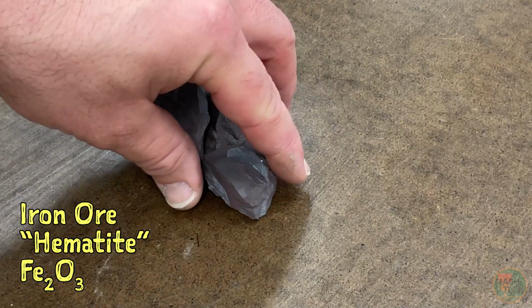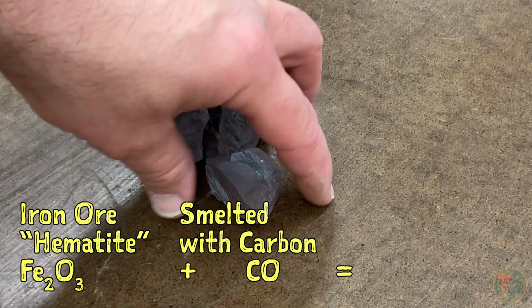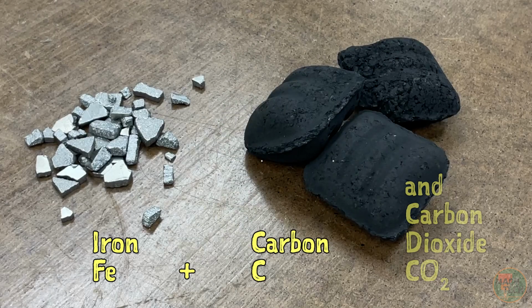Iron is mined out of the ground as iron ore, a mineral called hematite. This is iron oxide, basically a form of rust, Fe2O3. This ore is then smelted in a blast furnace with carbon-based fuel like coal or coke. Carbon monoxide from the fuel reacts with the iron oxide to form iron with a bunch of extra carbon in it, like maybe 4%, and then carbon dioxide as a byproduct.